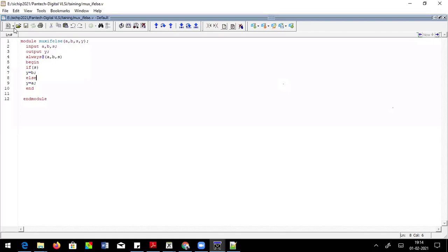Okay, look at here. When I say module, I was clearly mentioning that this port list, you can keep in any order. No way it creates a problem. The reason is I am explicitly defining here which is your input and output. But when it comes to primitive, you don't go there and say which is your input and output. In the primitive, the first one should be the output. In the gate level, whenever you write the code, the first one should be the output, subsequently following the input. Even the input order can change. That won't create any problem.